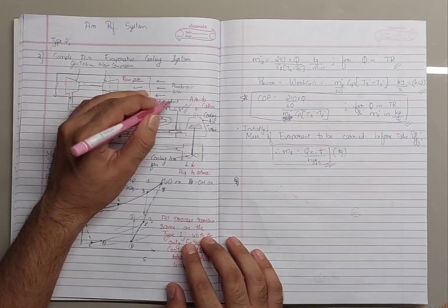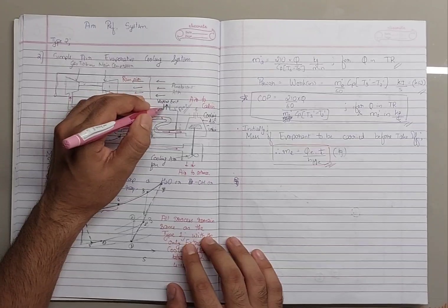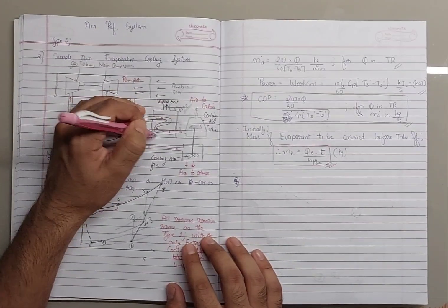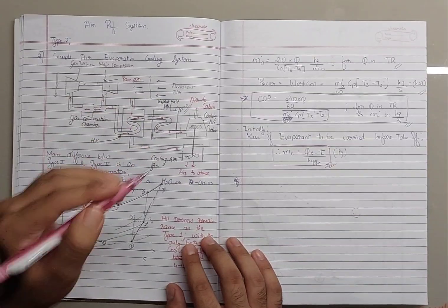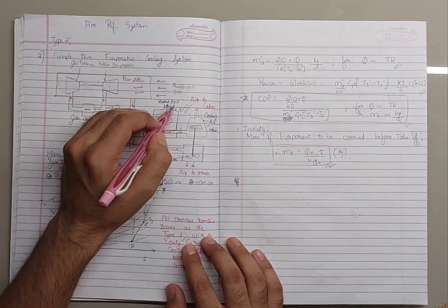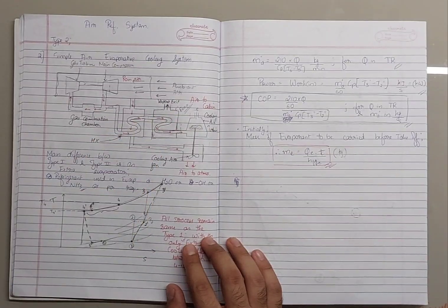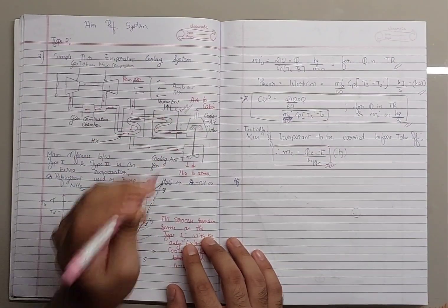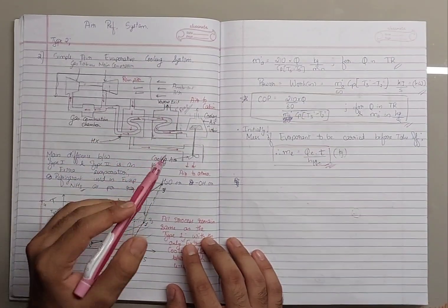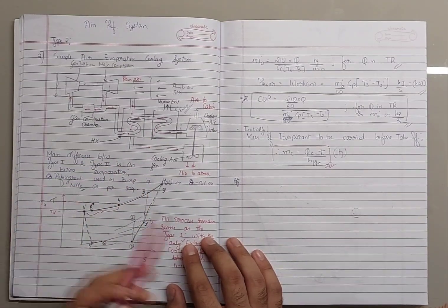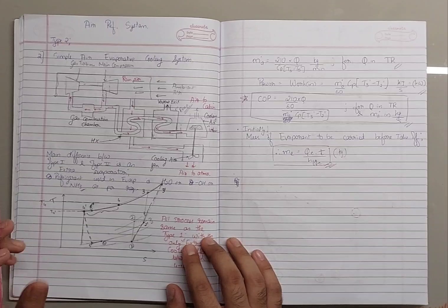Again, we can put a condenser here which condenses the vapor back to water, and the water is sent back to the evaporator. But this is an open case, so the evaporant definitely diffuses into the atmosphere and decreases over time. So we need a substantial amount of evaporant to make the refrigeration continue throughout the flight timings.